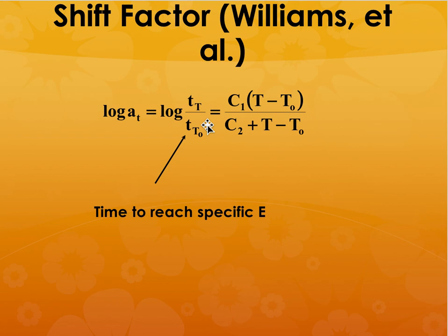The room temperature values are not going to be valid at a higher temperature. For steels, the room temperature data are valid even at 100 degrees centigrade, but for polymers they are not valid even at 40 degrees centigrade. So temperature and time connection matters for polymers.